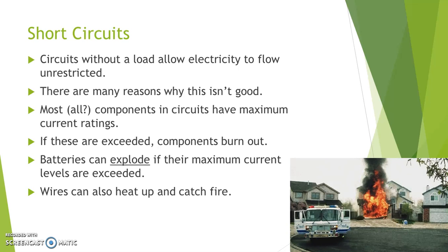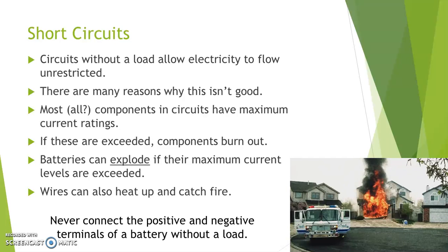So this was an example of a short circuit. Someone shorted across the leads of a battery, and it caused a fire and actually burned the house down. We don't want to do this, so we'll work hard to try to avoid short circuits when we build our devices in robotics class. And without a doubt, you need to be very sure that you do not connect the positive and negative terminals of a battery with any conductive material like wire or any kind of metal.